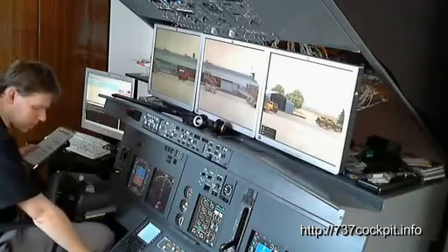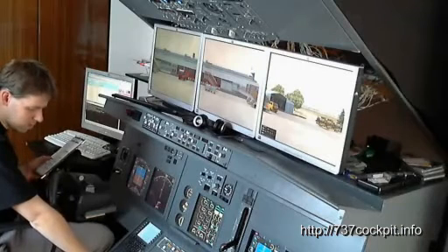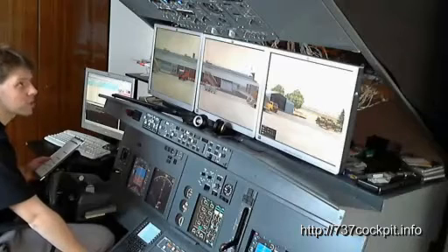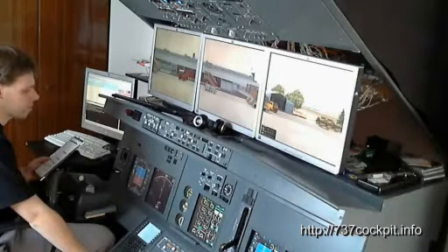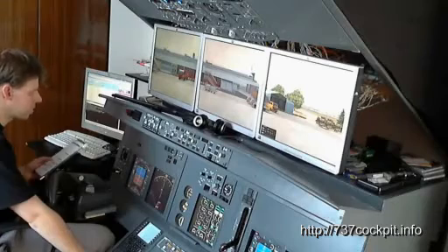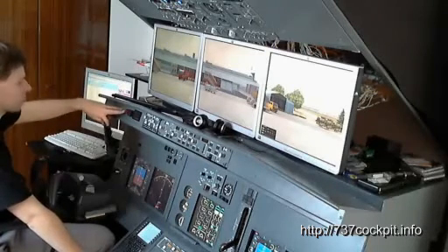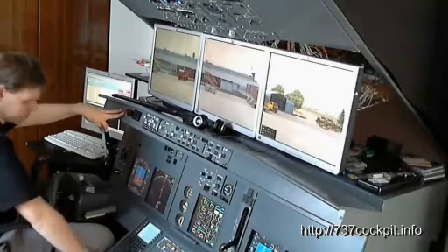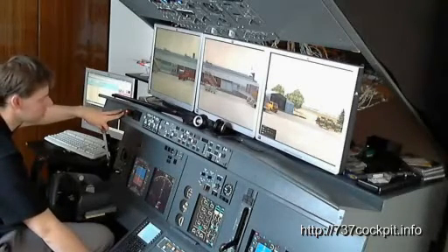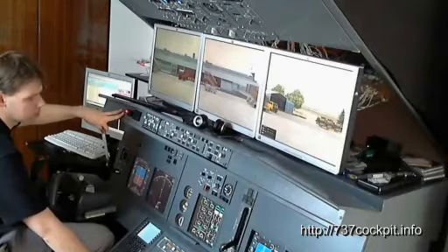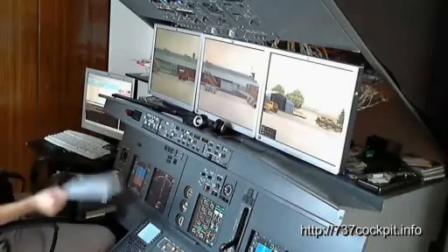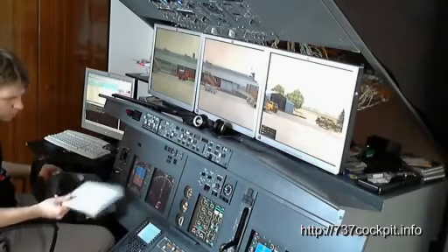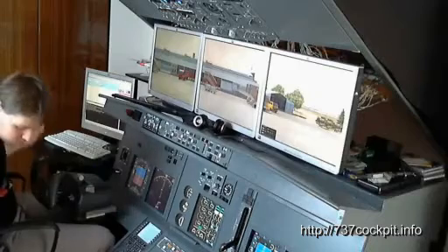Here is our new fire panel that is already installed, with a test switch. The test switch will light up the engine overheat on the fire panel, and we will hear a warning sound. Also the red fire button on the main instrument panel will light up. I'll give you a short demonstration of it. So as you can hear, the switch and the audio sound went on. That means our fire panel is switched.